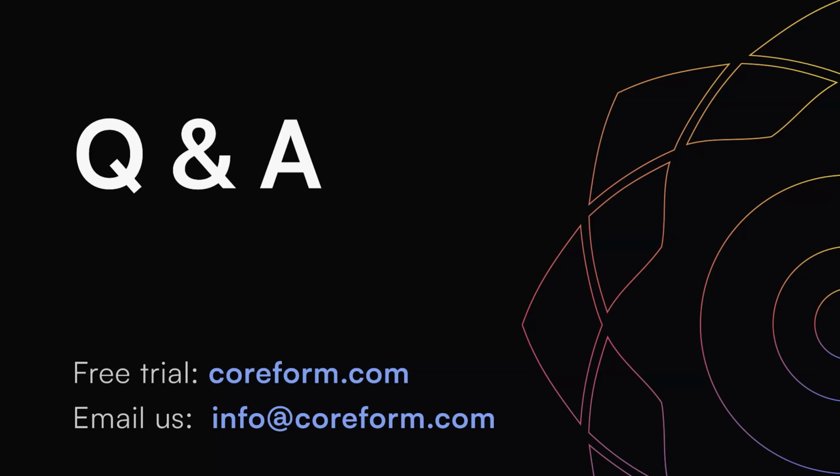From what I understand, they place a high emphasis on creating block structured meshes with high emphasis on orthogonality, which I kind of understand a little bit from a fluids perspective. The workhorse in Cubit is the pave and sweep algorithm, and paving just in general, the focus isn't orthogonality.